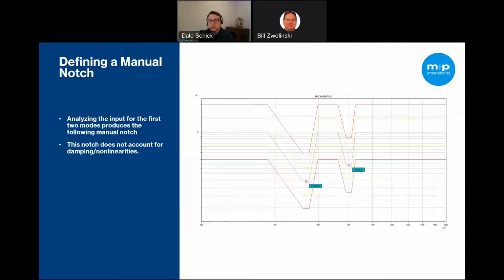So for the first mode, based on our calculations, the value drops from 0.1 G at the first part of the bathtub to 0.029 G. The second mode doesn't require as much reduction, but it ends up at 0.0438 G. This has a more aggressive slope, however, so this more aggressive slope due to the lowly damped Q is applied here.